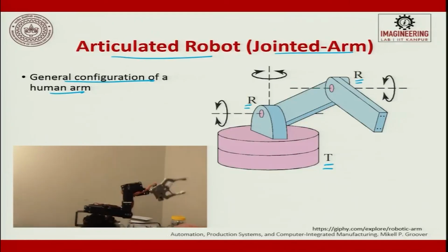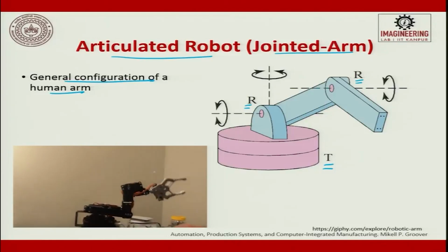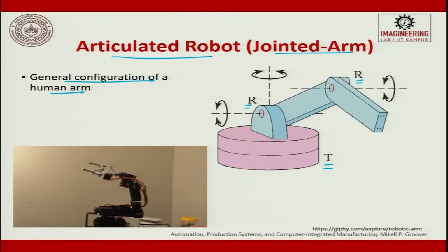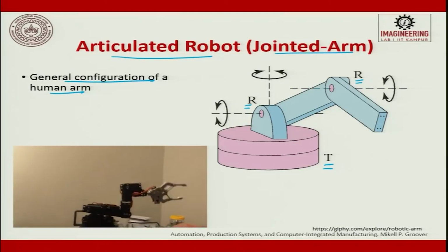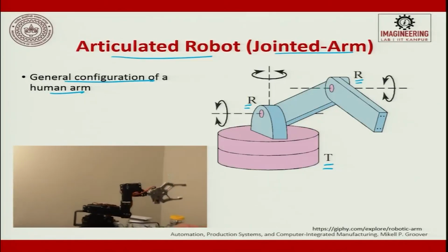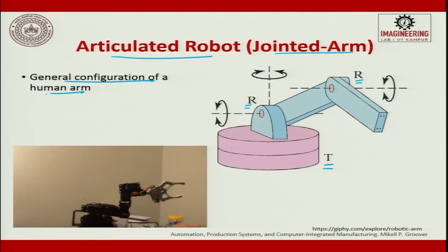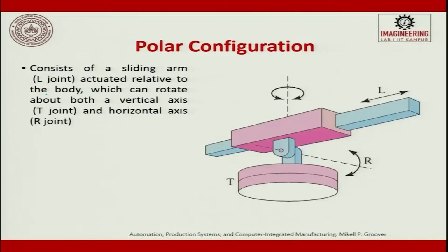You can do much more, but the only problem is if you have more weight in the end effector, it will topple, stability becomes a problem. So, the biggest challenge is how do you make the manipulator, how do you make the links, how are you going to activate those links. Here it is typically a pick and place or a gripping robo only. So, articulate robo can otherwise be called a human arm robo.